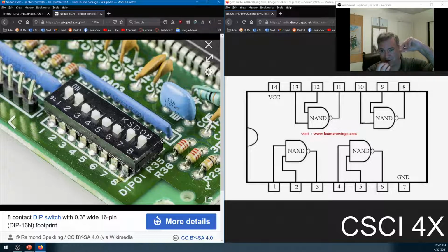And you get a little suction cup thing. You suck the solder out of it. Do the same to the other side, then you can pull the resistor off. And that's how electronics repair works in a lot of cases.